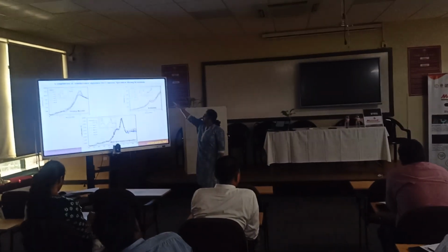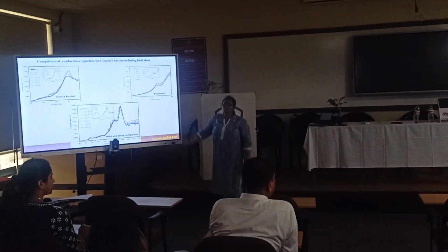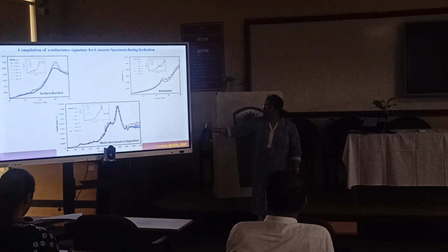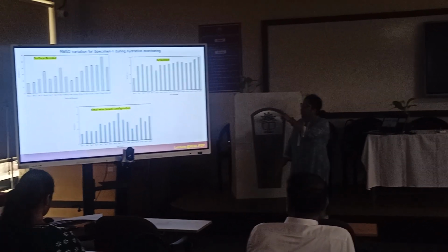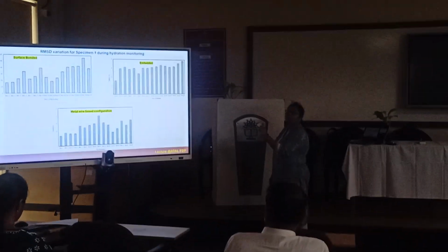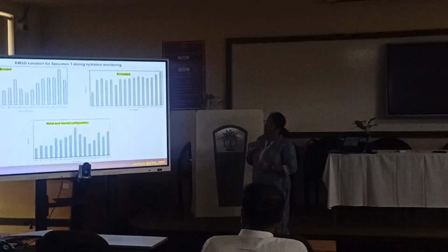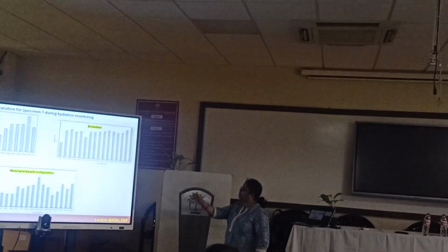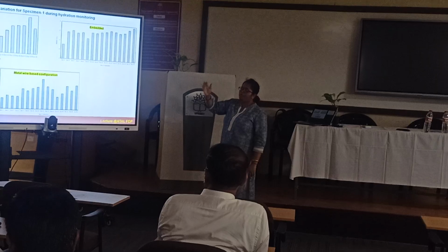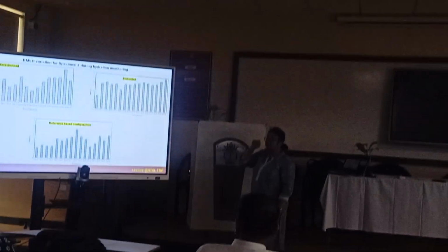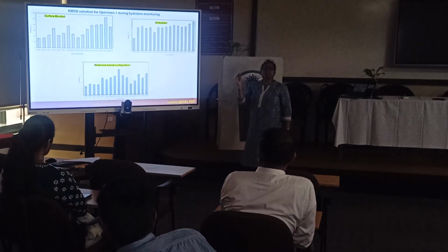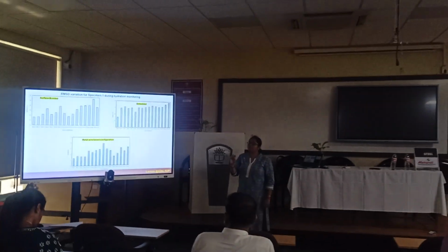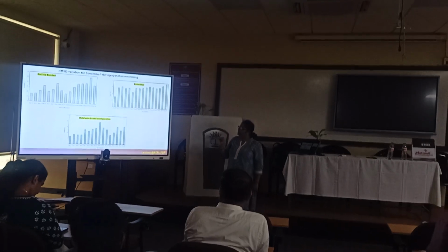Small figures, the inside figures of the graph, are for 1 to 3 days, and the others are for 1 to 28 days. Now, looking at this RMSD, we take the baseline signature, which is to be intact, as day 1, because this is the baseline from day 1 after molding or casting, and we compare the same signature from day 1 and do this RMSD variation. RMSD is the root mean square deviation of signals, because here we are talking about signals, so we use that as one of the damage metrics to understand.